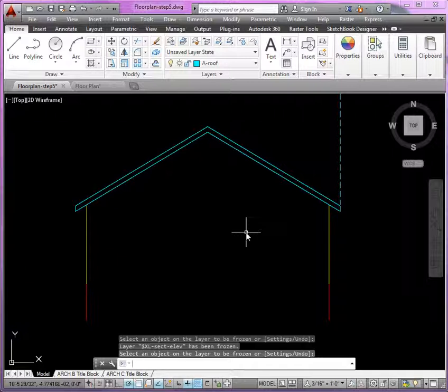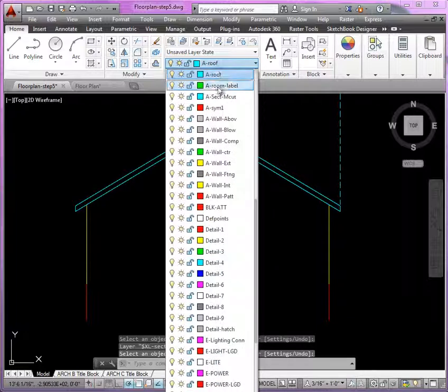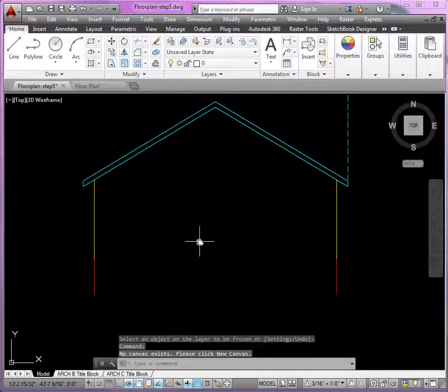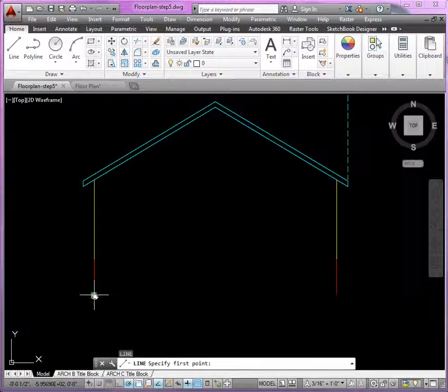Now, we definitely want to represent the ground plane. So what we'll need to do is actually draw in the line there, and we could use layer 0 for that. That would give us a little bit of weight to the drawing view if I just simply draw a line that represents the ground plane here.